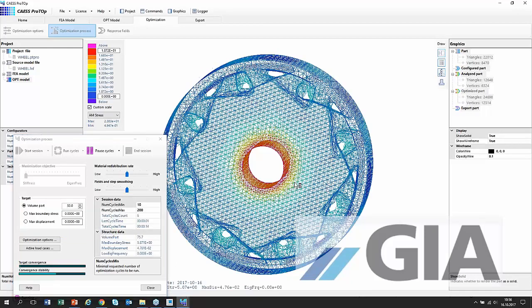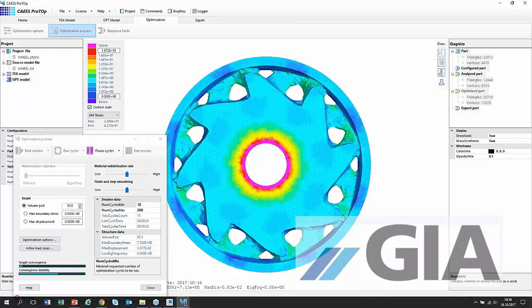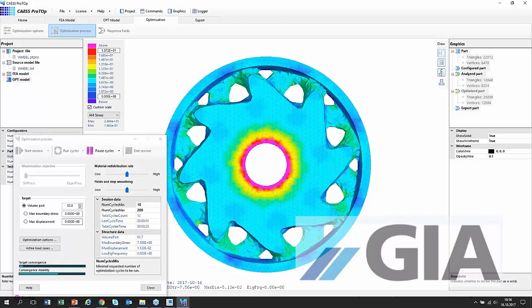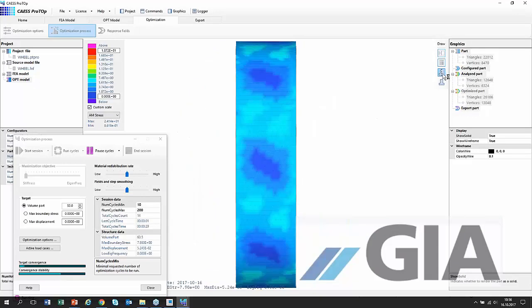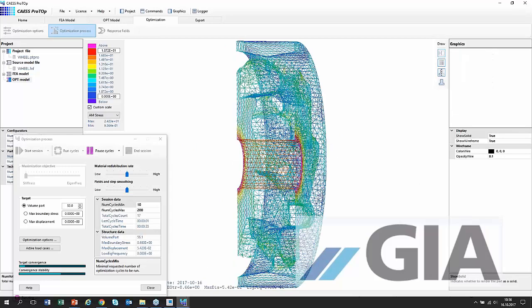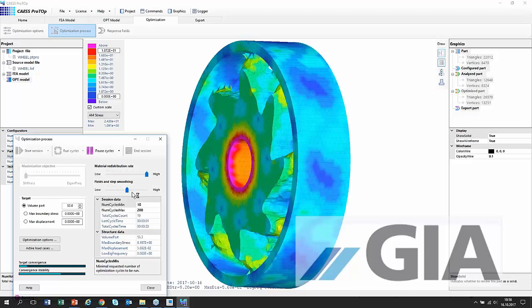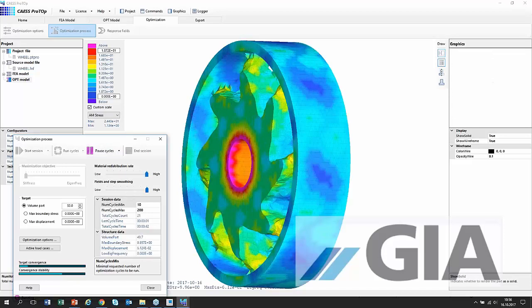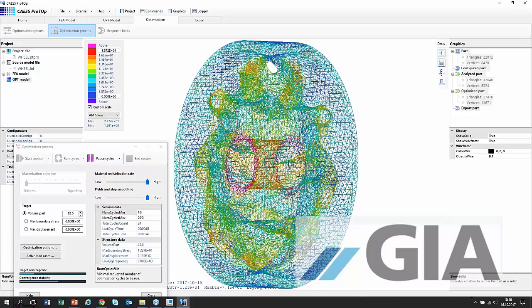And now when I'm looking here from front, you see, okay, this wheel can be casted because there is draft angle on it, and it will be opened from the, let's say, middle datum plane. Let's have a look here at the cross section. Okay, component looks like that. And right now I'm a little bit in a hurry, so I'm taking out the material a little bit more aggressive, and you see, okay,